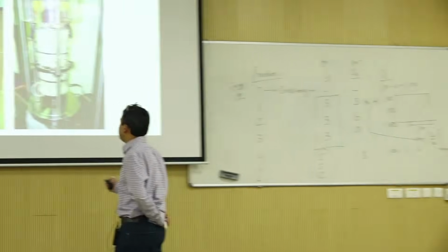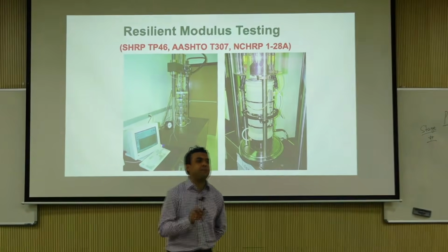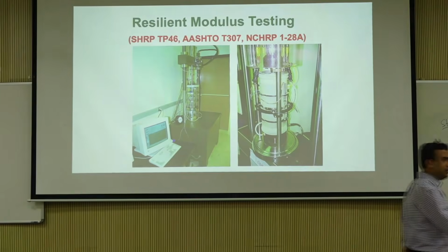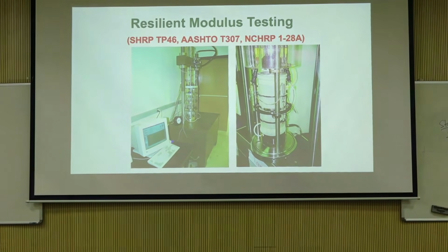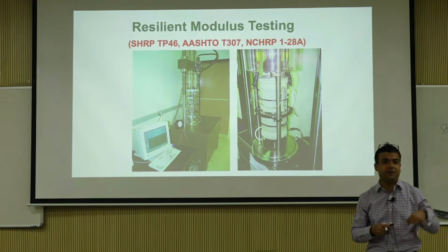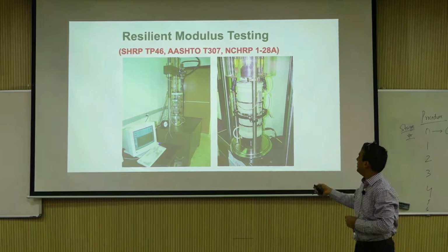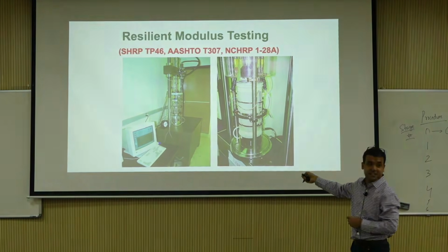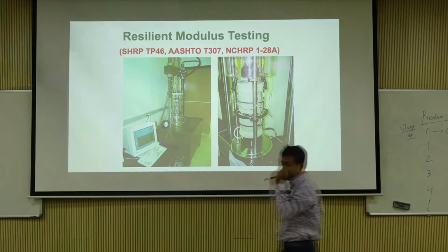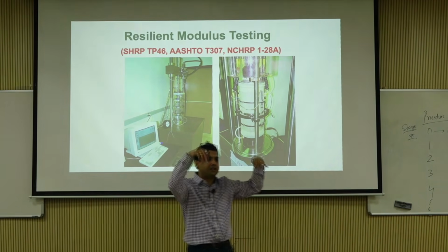And test setups, traditionally, when systems were developed, and I think that's true even for the system that you still have, the external LVDT, right? The simplified one I have is also external LVDT. Your LVDTs are outside on the system. It's not mounted directly on the specimen like this. But AASHTO T307 allows external LVDTs.